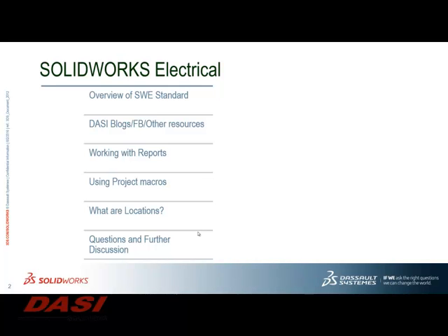If you're designing a control panel, is it easy to put that into SOLIDWORKS Mechanical onto a machine? Oh, yeah. Because you assign that where you've got that component, where you see the library manufacturing part, you can assign a 3D model to that unit.